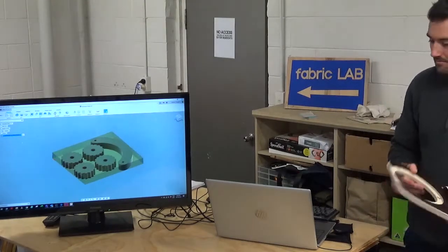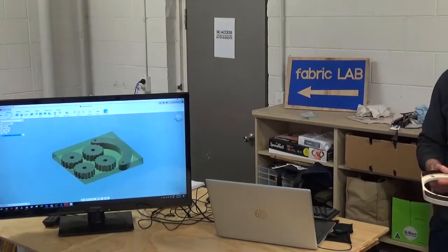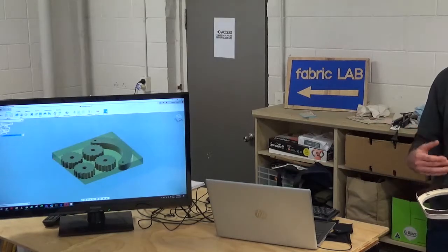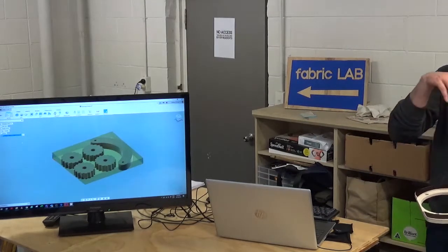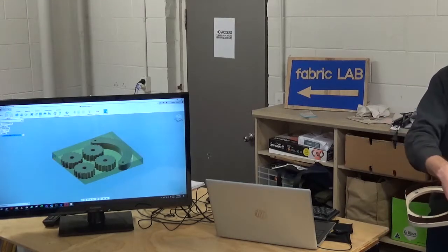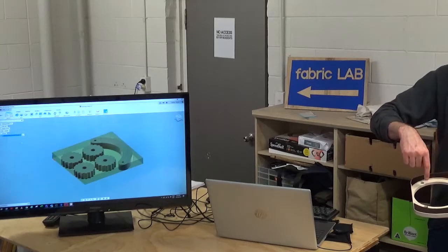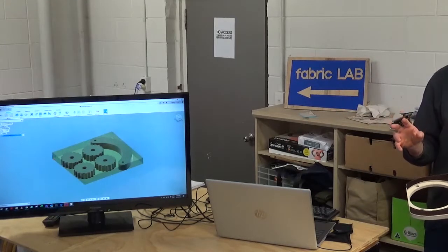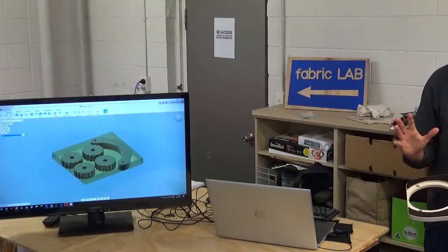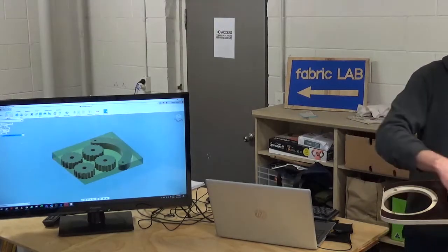Did you do all of the operations of the same type together? Yes. The three drills were all one operation, and the two pockets were one operation, so that and that were done together. The profiling can be done together too, but basically you want to cut inside, then outside.